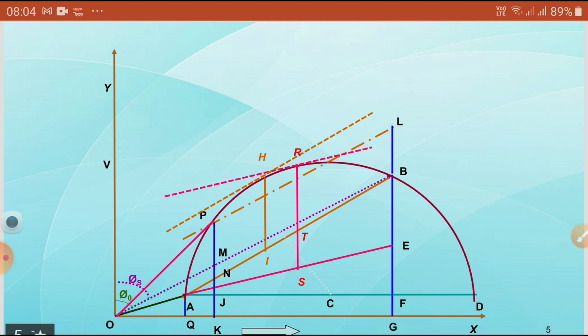And at the same time, if you add a further 2 kg load, the speed will reduce to 1400 RPM. That means the slip is increasing. So 1440 is one slip, 1420 is another slip, and 1400 is another slip. During this changing slip, how does the stator current I1 change? That can be represented in a semicircle, which is known as a circle diagram.